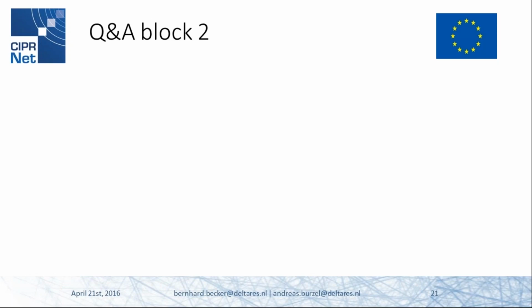Yeah, this depends on the case, of course. The general recommendation is that you start with external coupling and analyze the results. And in many cases, if the time steps are small enough, then this will do it. We've also published a technical exercise on this topic that can give some guidance, and the reference can be seen in the accompanying course material that we will provide with this webinar. But if you find that this is not sufficient, then it might make sense to apply iterative coupling.